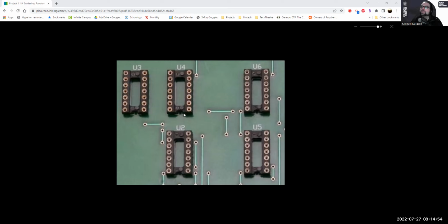And it'll be a little confusing for them if these half circles are on the top when they're supposed to be on the bottom. The chip's got to go in the right way. The socket doesn't matter as much. I'll usually give them a little guilt trip, like, well, in 30 years, when this chip burns out and somebody's got to replace it, they're going to look at the socket to guide which way the chip should go in, and your socket's going to be upside down. And they're like, should I resolder it? I say, no. Don't resolder it.